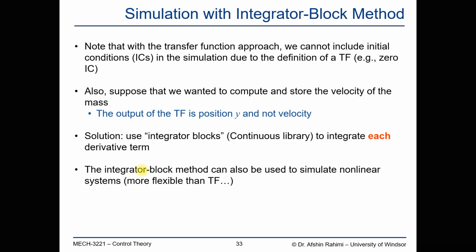And next we get to the integrator block. Note that with the transfer function approach, we cannot include initial conditions in the simulation due to the definition of the transfer function. Also, suppose that we wanted to compute and store the velocity of the mass. Remember, in here, we are only able to obtain